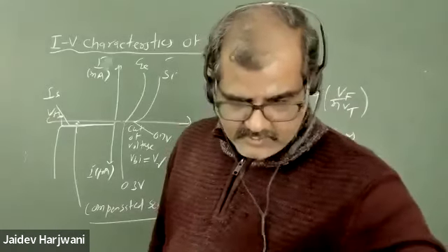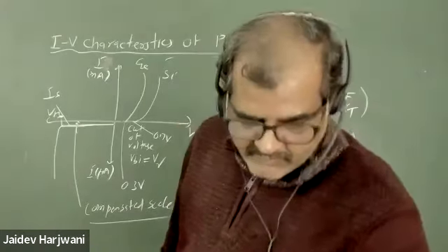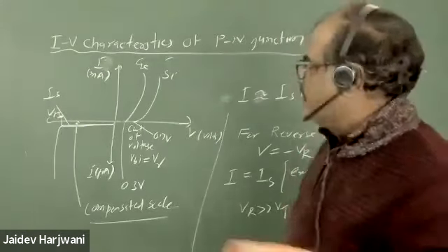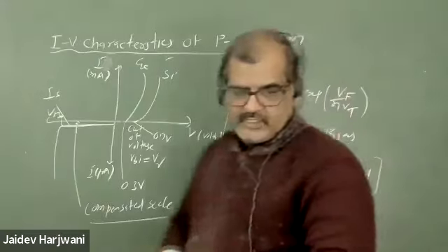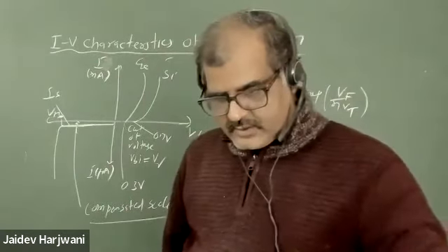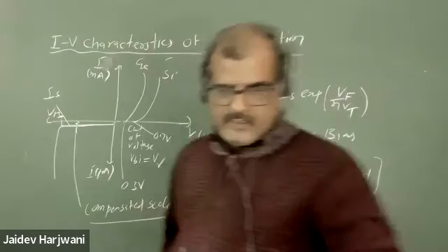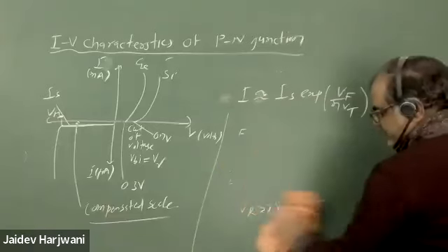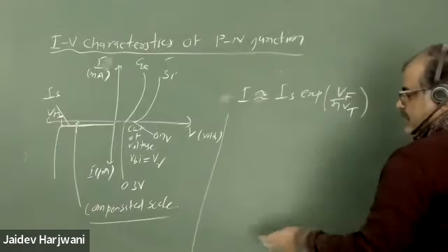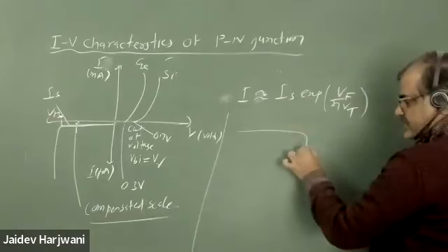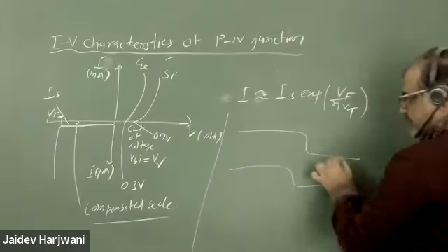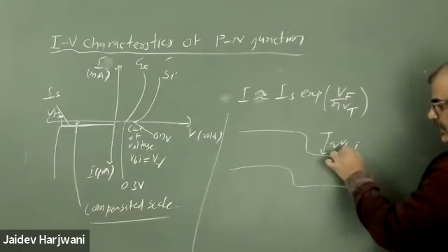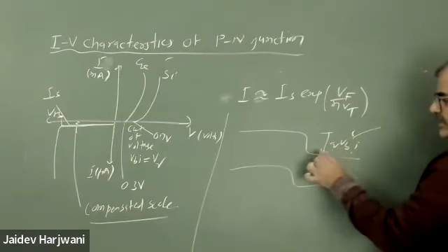Sir, what is cutoff voltage? Cutoff voltage is the minimum voltage required for the diode to conduct. Does it mean some fixed amount of voltage only? VBI is fixed for every diode. I showed you the energy curve, where you have this qVBI. Until you apply a voltage greater than this VBI...